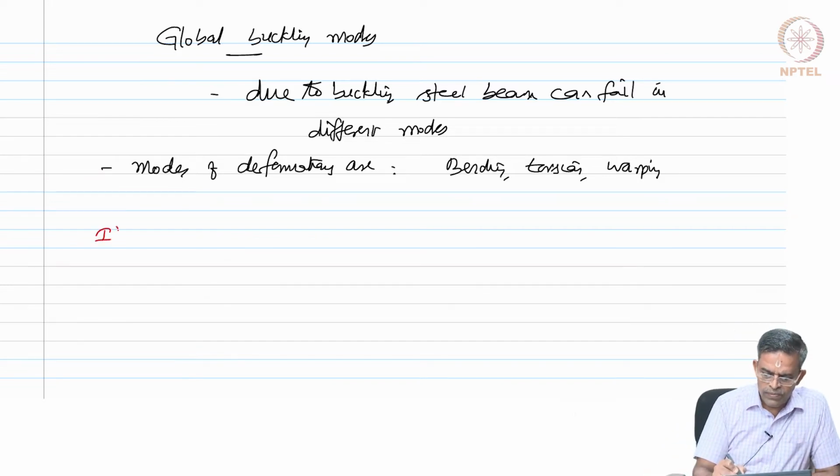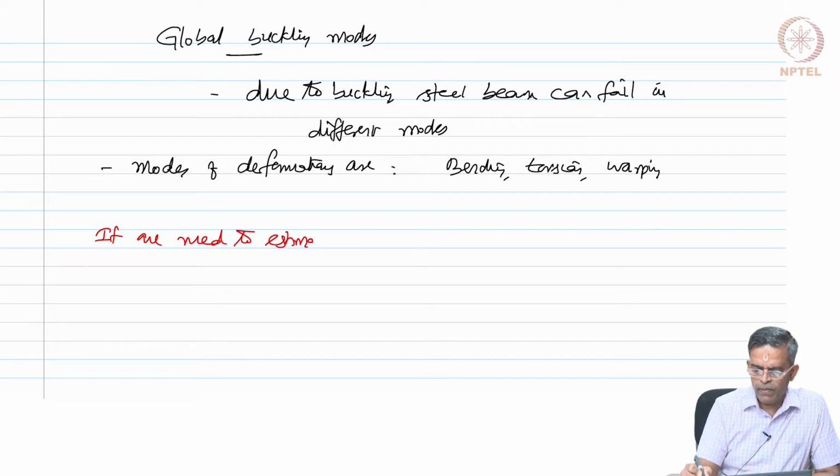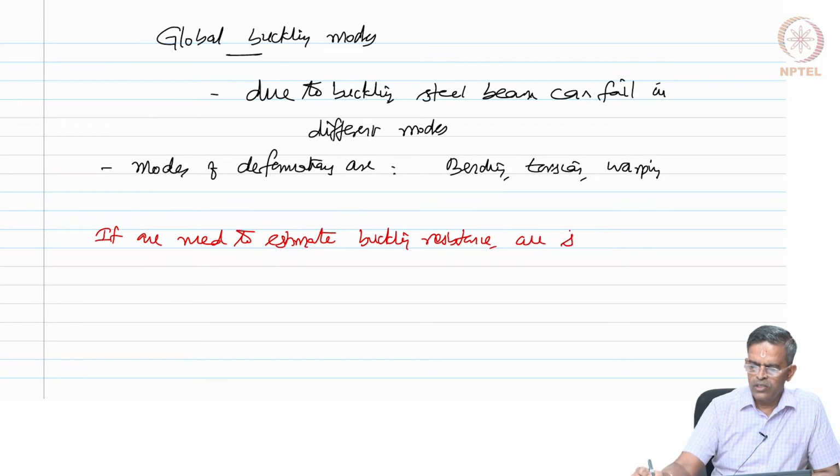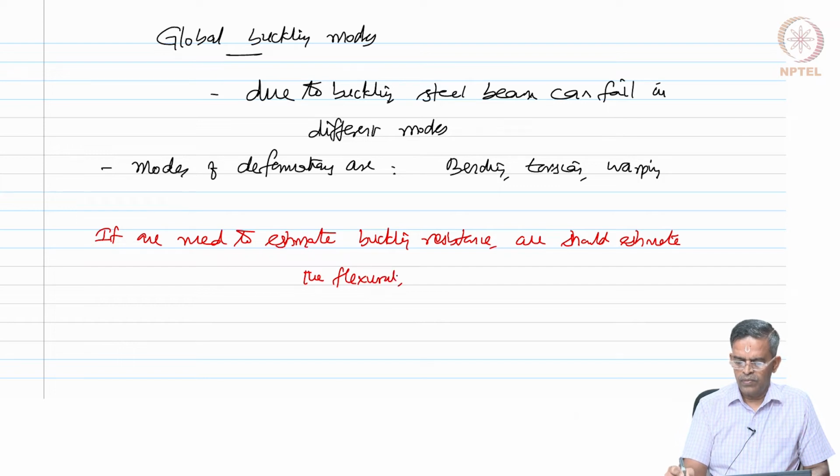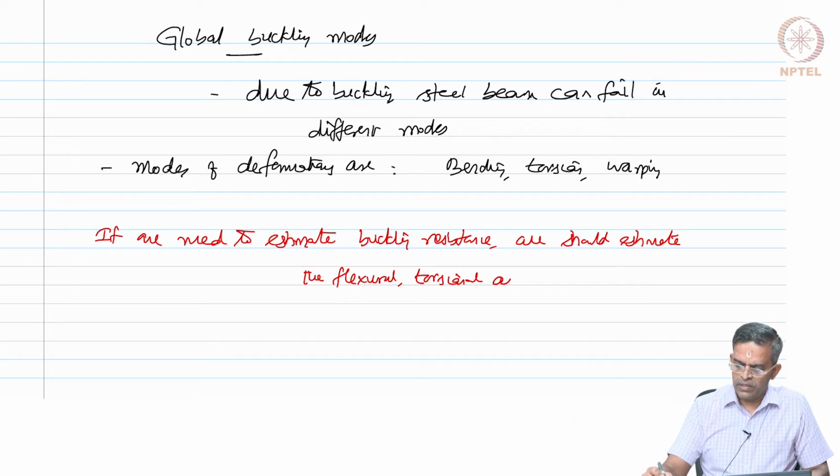So, if one needs to estimate buckling resistance, one should estimate the flexural, torsional and warping stiffness of the beam.